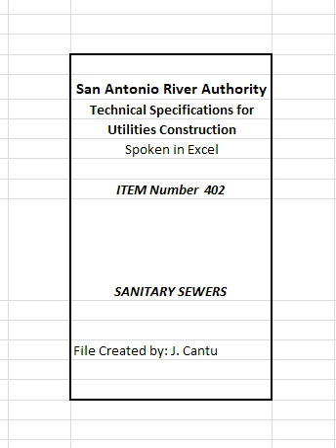m. For each additional wash bay over 4 single bay or portable washer type vehicle washes shall install a 20 GPM interceptor minimum neutralizing devices. In no case shall corrosive liquids, spent acids, or other harmful chemicals which might destroy or injure a drain, sewer, soil, or waste pipe, or which might create noxious or toxic fumes, discharge into the sanitary sewer system without being thoroughly neutralized by passing through a properly constructed and acceptable neutralizing device.